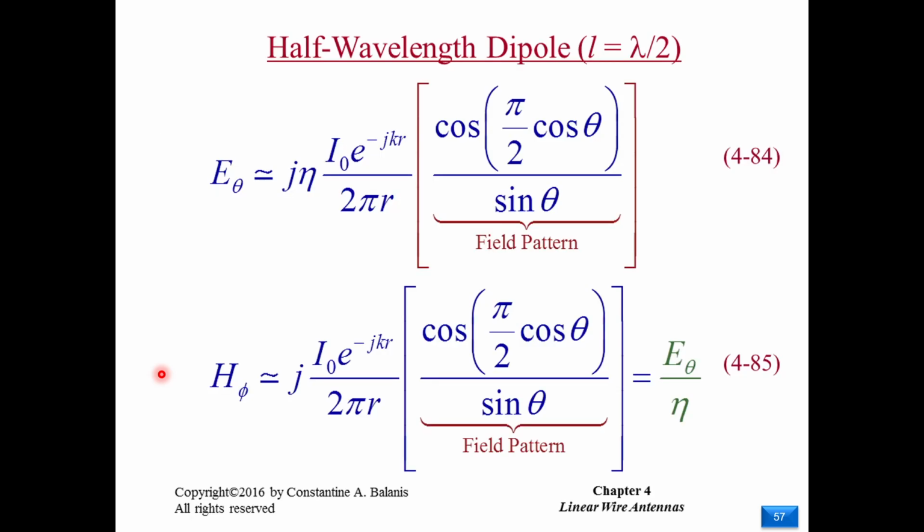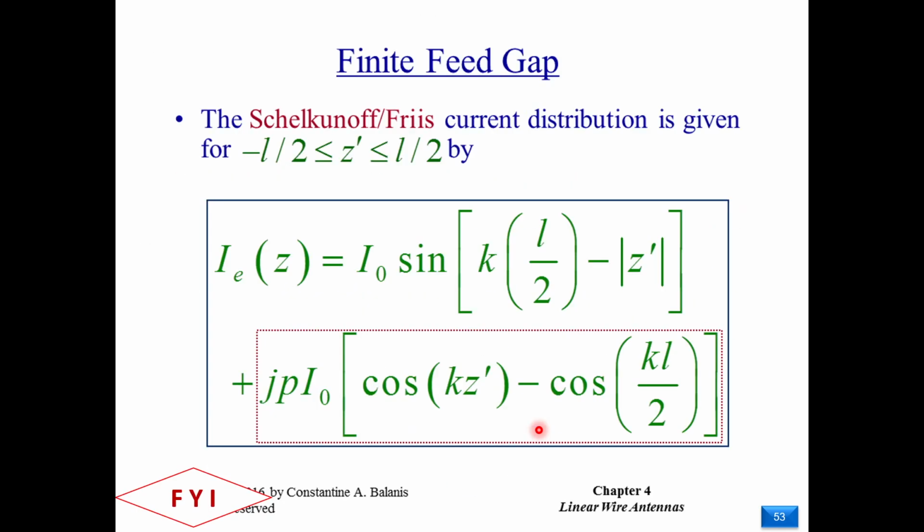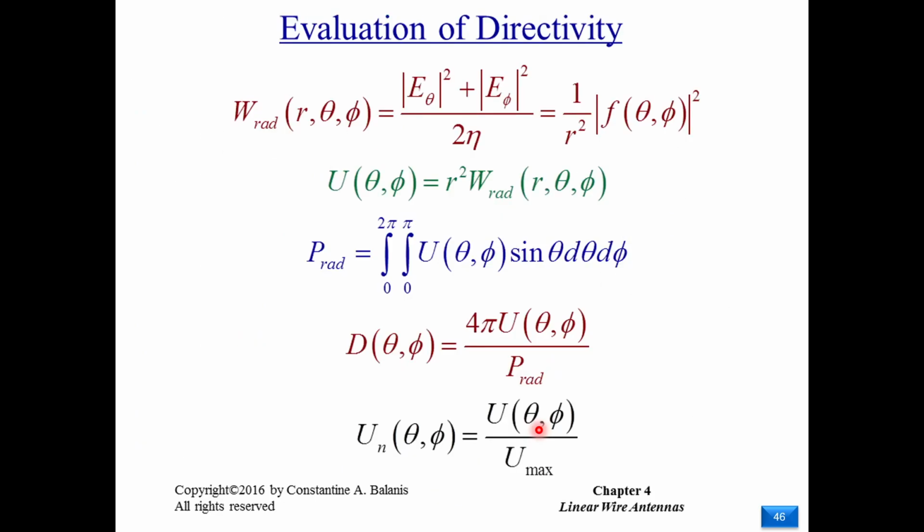Welcome everybody to the second part of lecture number 4, where we're going to start by discussing a special case of the wire dipole antenna, which is the famous lambda by 2 dipole. In terms of analysis, it's the same thing as the arbitrary length dipole antenna. The current distribution would lead us to find E theta and H phi of this format. So we just go back to the first part where we did the analysis.